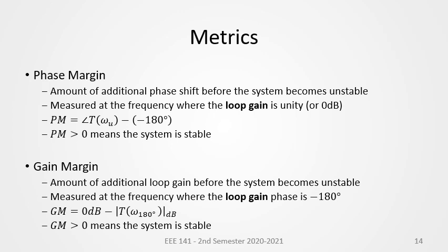Note that it is also possible that the phase and gain margin must be measured with respect to the positive 180 degrees if the phase change tends to increase towards that direction.